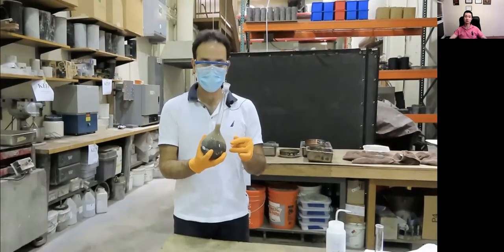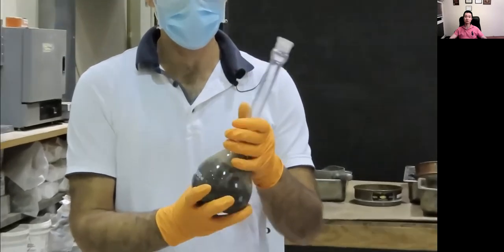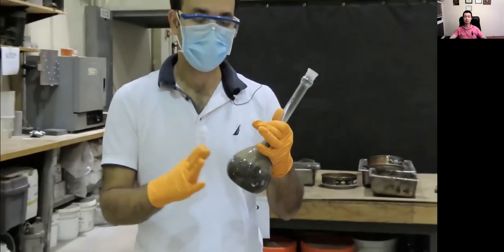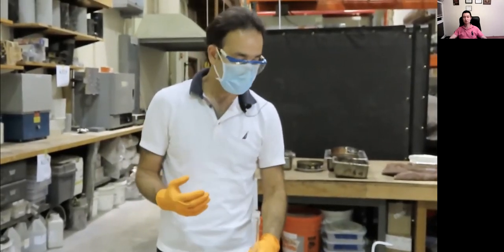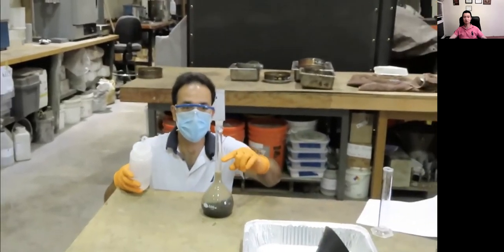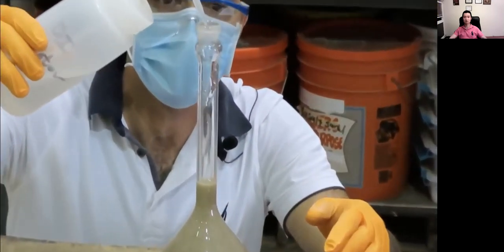Okay, I'm done with agitating and getting rid of the bubbles. I can see no air bubbles on the surface of the pycnometer. It means that I just have the aggregate and water that fill the whole capacity. What I need to do is just add more water, because the line is right over here. I need to add water to get to the line and then weigh the whole thing.